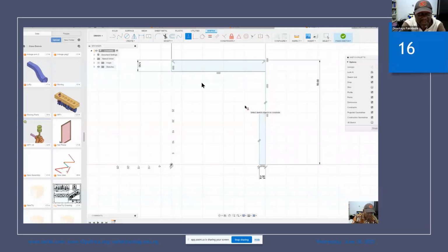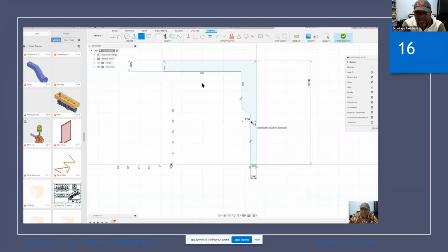We should have picked the dimension tool first. So we go back again, pick the dimension tool, yes, pick that one, then take that to there. The horizontal distance there is 7.5. Okay, so we then do the same thing again and get this vertical distance. Vertical distance there is 20. And then the vertical distance between those two is 4.